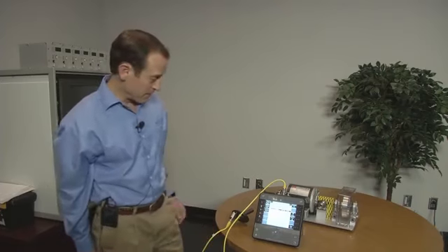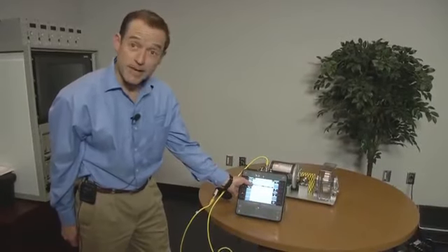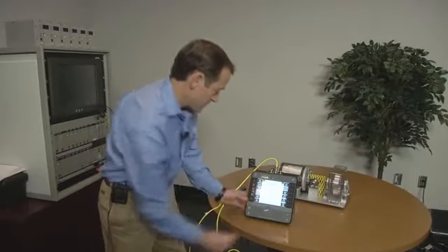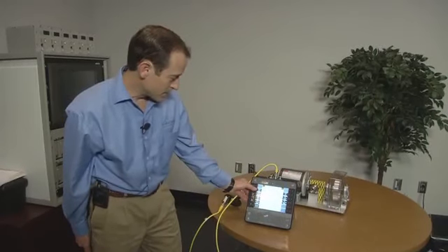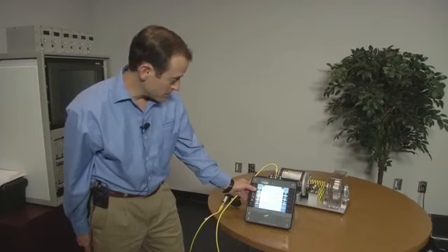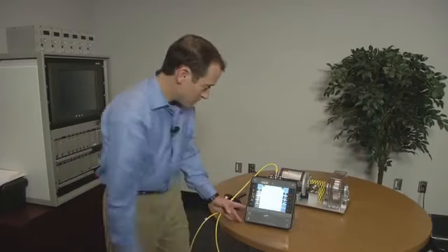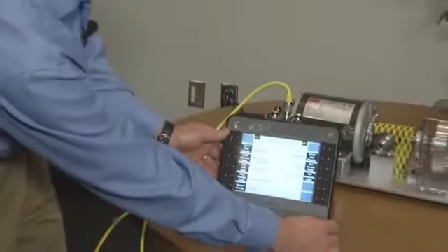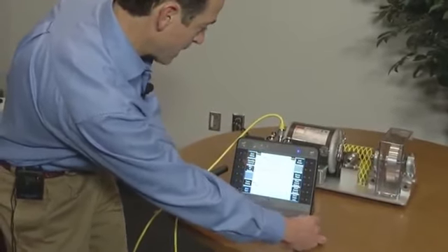So to set up this demo, first go into Route Manager, select the Spring Mass route, and then go to the Alt tab, hit User Setup, and in User Setup, the Select Data Display should be set to Waveform. The Select Live Display should be set to Waveform, and the Auto Advance should be turned off. To begin the demo, hit the Alt button and the Back button, and that goes back into route mode.